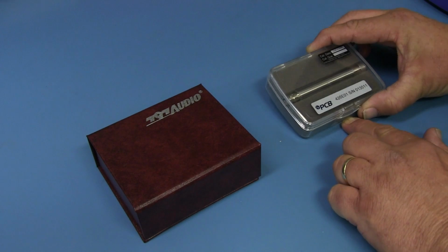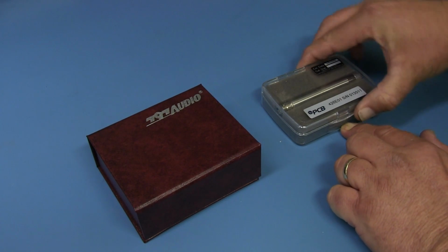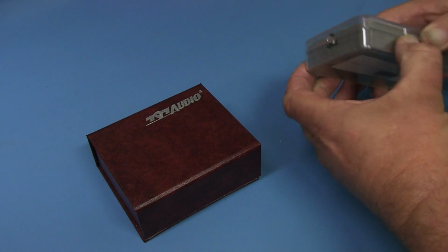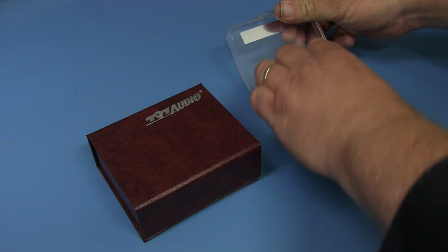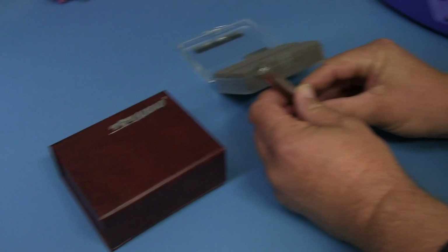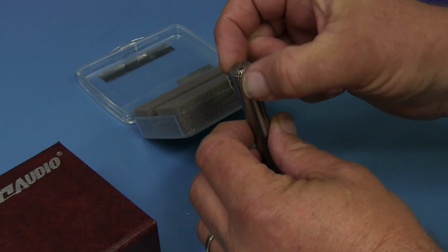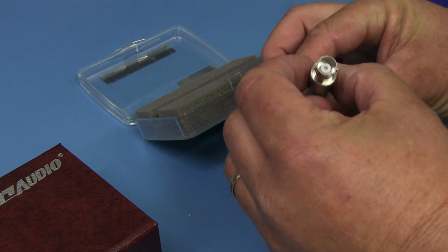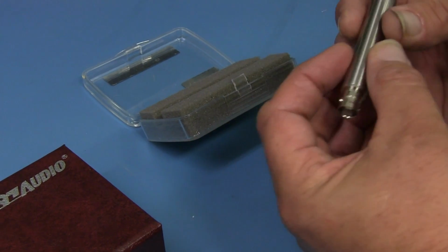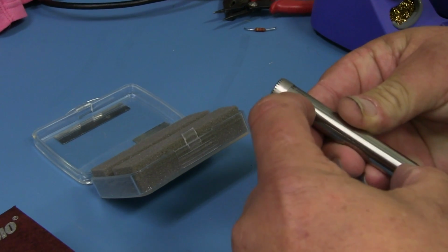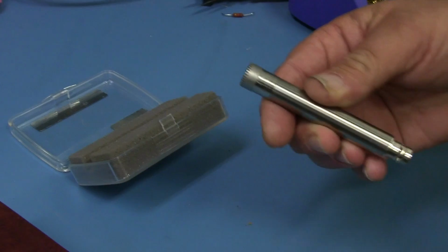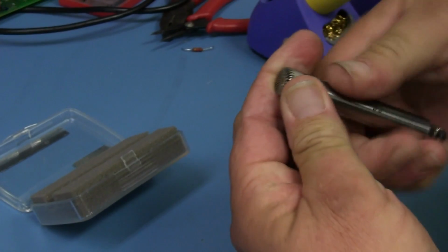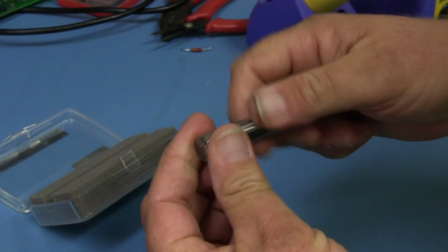One of them particularly, this one from PCB Piezotronics. Yeah, I know them. It's my main measurement microphone, and if I can remember how to open the damn thing. Okay, it's a half-inch measurement microphone, half-inch diameter there, with a nice simple BNC connection. BNC straight out, nice. There's actually a reasonable amount of electronics in the body. The actual microphone is only just that tip. Yep. And in fact, oh, no, that's fairly tight. Oh, here we go.